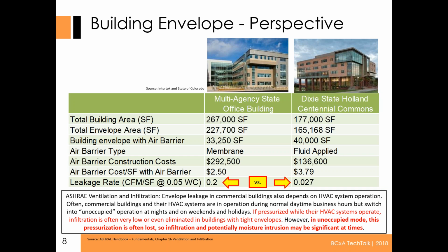So if you are looking at building pressurization and that's part of your sequence, part of your focus, part of functional testing, make sure you're looking at the trends during the off hours, because that's where they say unoccupied mode pressurization is lost, infiltration, and potentially moisture intrusion may be significant. So important pieces. Hopefully I'm hitting on things for you to think about and remember.